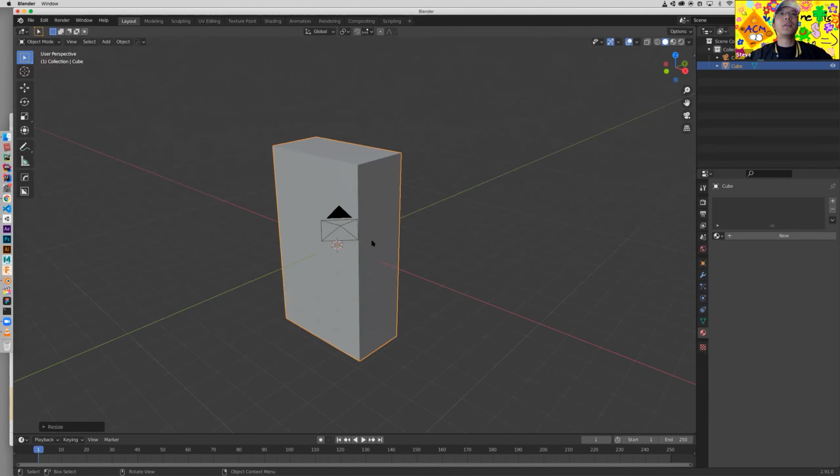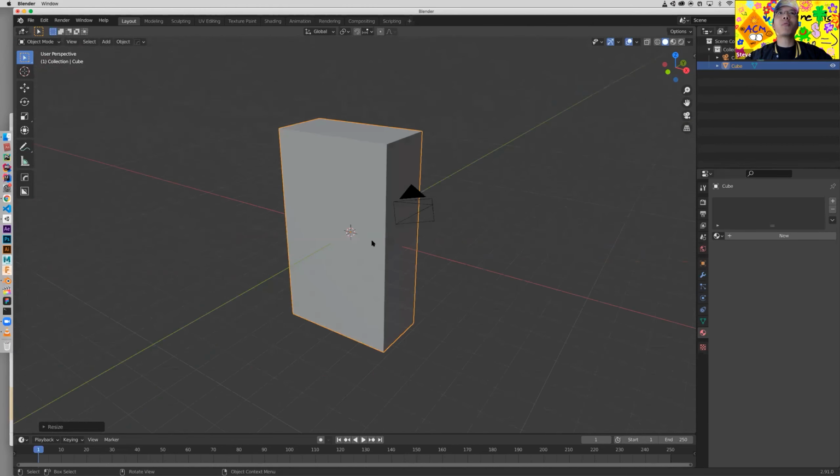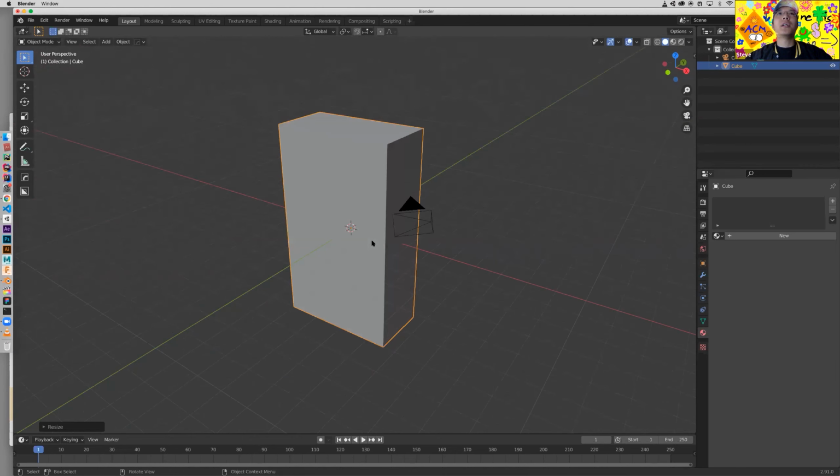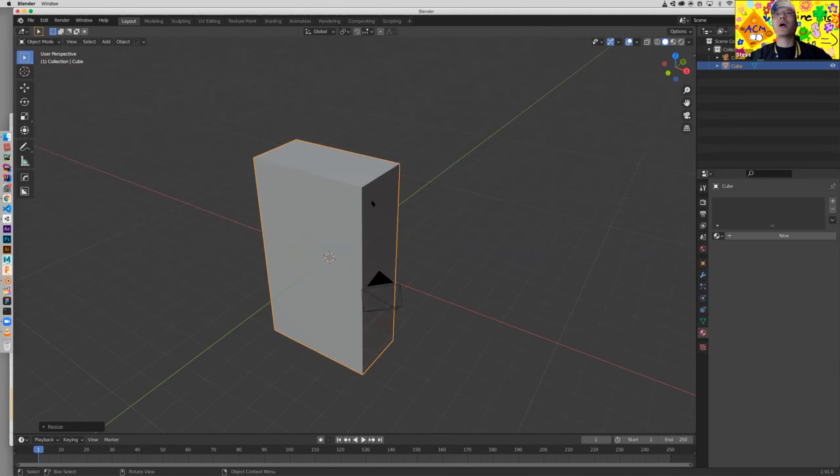And notice that this is not always a good idea, because we don't have individual access to specific components of the shape. If we want to edit maybe a single vertex or a single edge or face, how can we do that? We can enter the edit mode. So we're all gonna hit Tab on your computer.